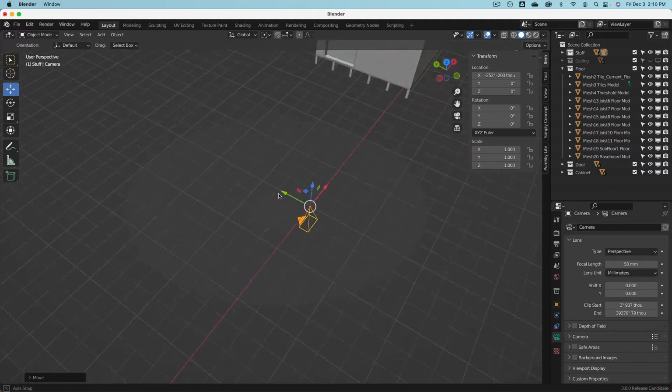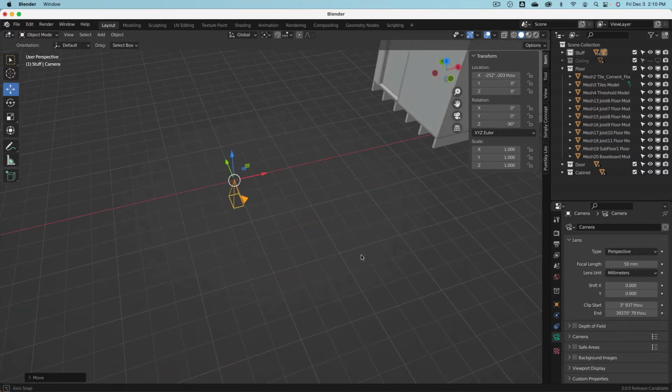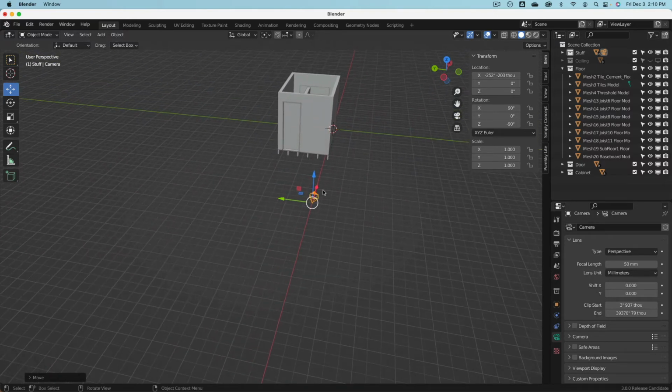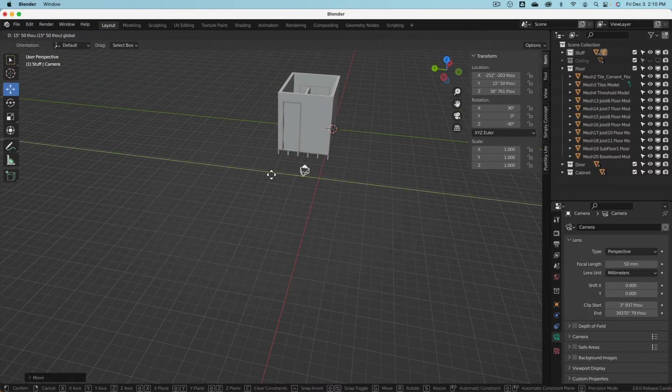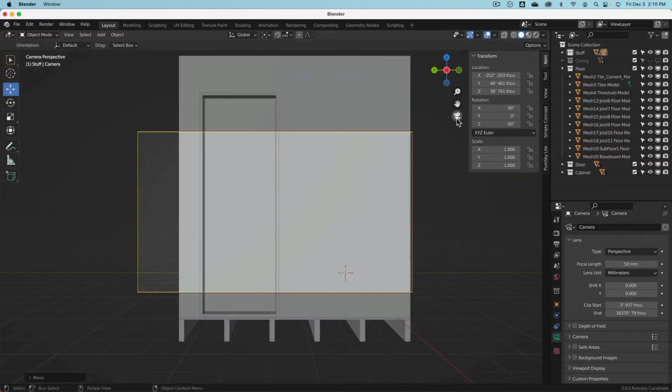The orientation is all wrong. So now you see we need to rotate this one along the z-axis, so minus 90. And then we need to set the x-axis, yeah, 90 degrees. Okay, so now the camera actually looks up. Then I can move it up and bring it over. If I go into the camera view, I see, well, beautifully the space.